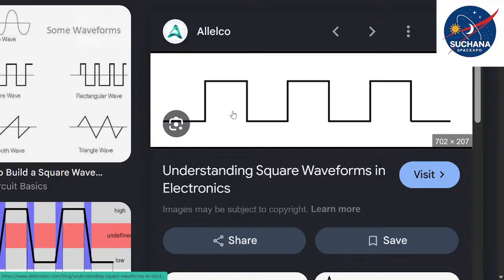Okay, this is the very first point that you need to understand. Different boards operate at different voltage ranges. Okay, operational voltage range. So ESP architectures operate at 3.3 volt, whereas Arduino UNO operates at 5 volt. That means in order to run the Arduino module, you need to give a 5 volt input power supply. You can give it from a battery, or you can power up the Arduino module directly from your laptop. Similarly, you can also power up an ESP32 with your laptop.